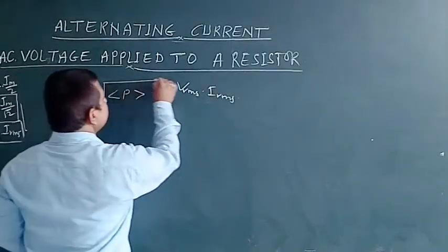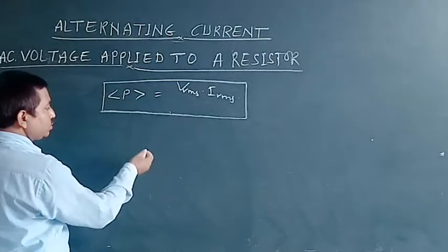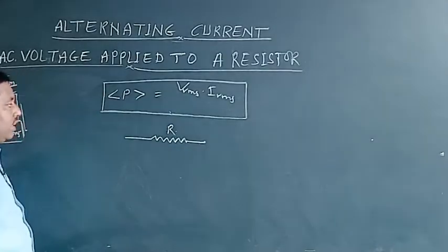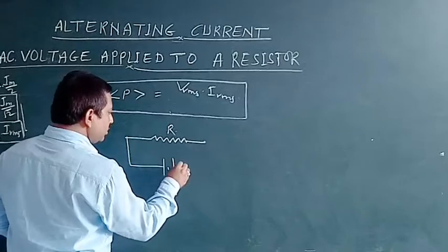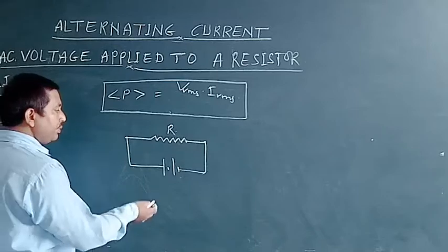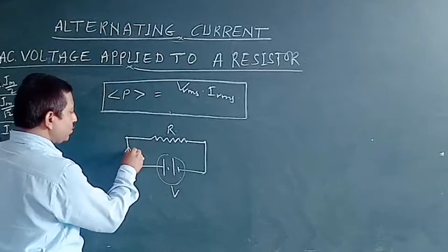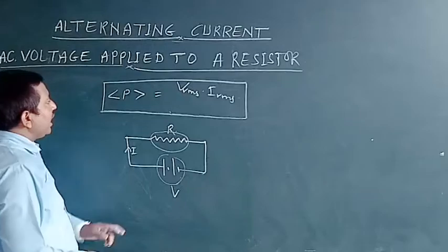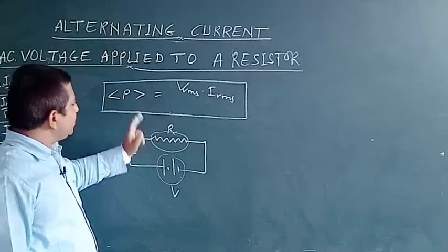It means suppose this is a resistor whose value is the same as that of the resistor connected in the AC source, and it is connected to a particular DC source, with current I flowing through R, and the same amount of power is dissipated as the power dissipated in one complete cycle in the resistor in the AC source.